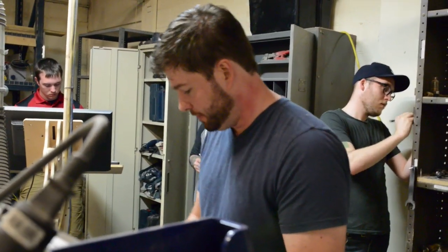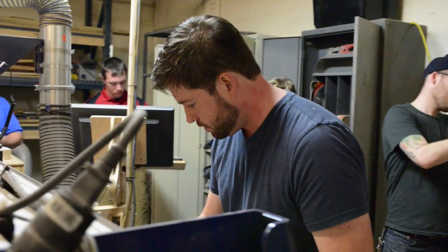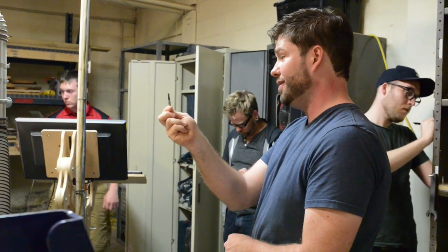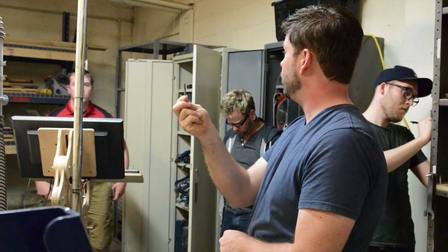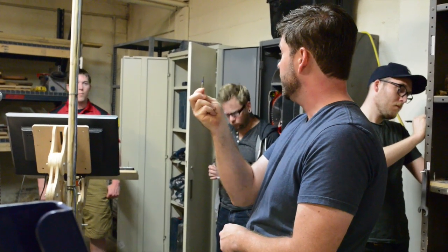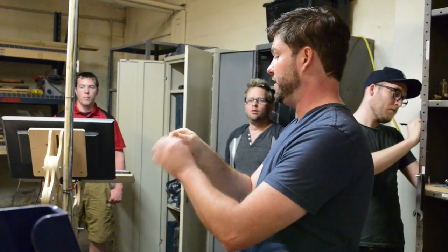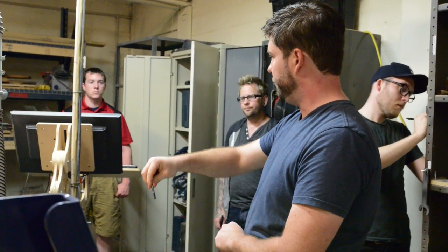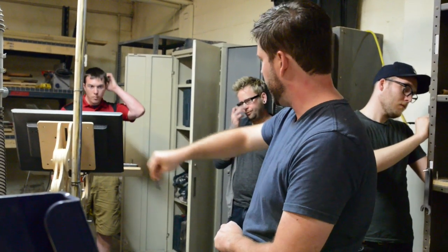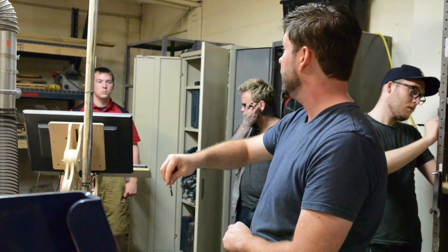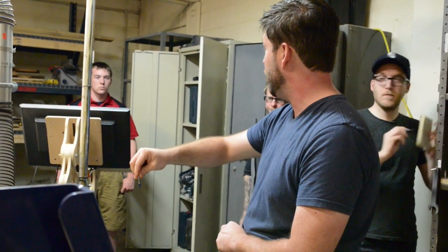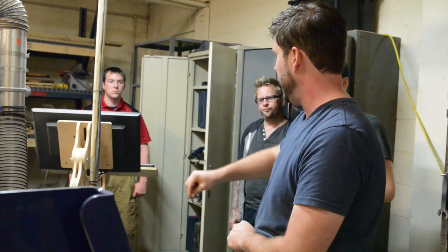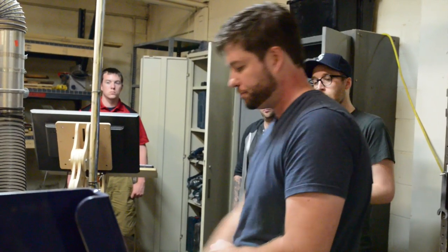So we're going to use this typical, just 2 flute, straight cut, very standard 1/4 inch woodworking bit. This is what we're going to use for our profile. Remember, this is just going to go down 1/4 inch, and go down to the full 1/2 inch and then cut it out. On that last pass, it's going to go around and it's going to know that the tab is there. It's going to come up and not cut the tab out. So we're going to use that for this.